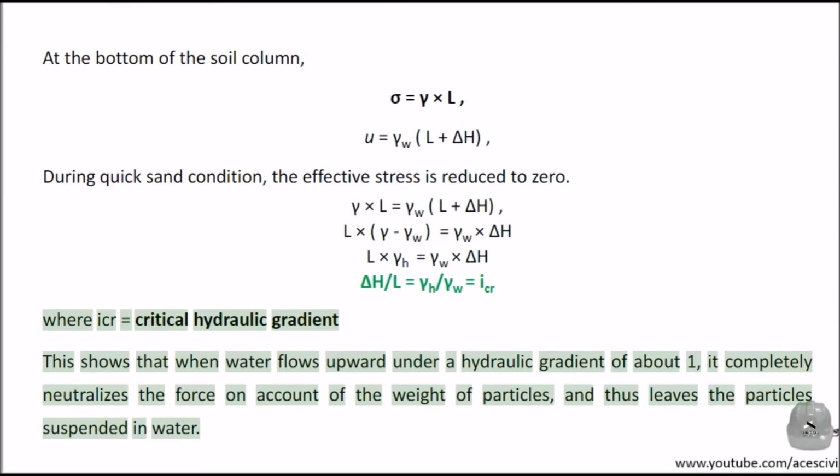This shows that when water flows upward under a hydraulic gradient of about 1, it completely neutralizes the force on account of the weight of particles, and thus leaves the particles suspended in water.